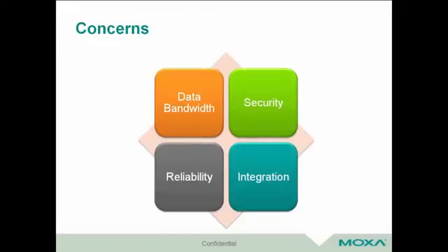And lastly is the integration. If we think about integration, we think about there are legacy devices in those cabinets out in the field. There's serial controllers out there that probably still use RS-232 communications, 485 or 422 communications. And the next question is, how are we going to route that back? We have existing sites that already have this, and how do we expect to pull all that information back without having to make a complete retrofit of that whole environment? There's definitely technologies, and I'll discuss that with you as we proceed through this presentation.